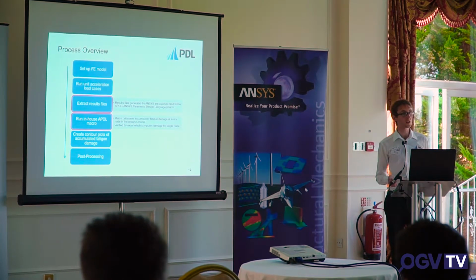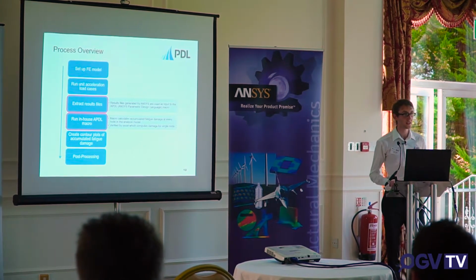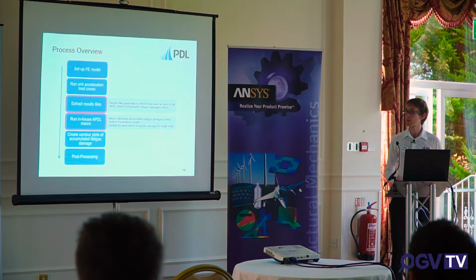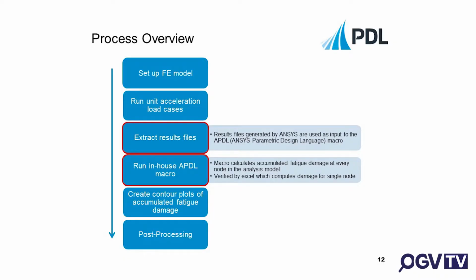Okay, so there are the FE models. We run the unit acceleration load cases. It's very simple to do that part. Then we're going to extract the results files and feed them into our APDL macro.